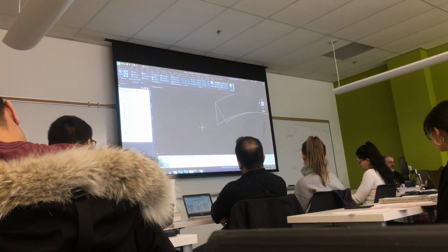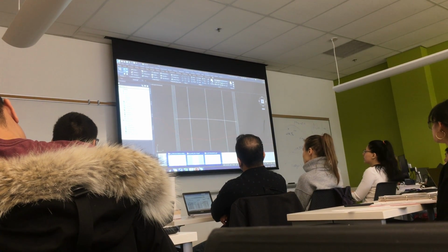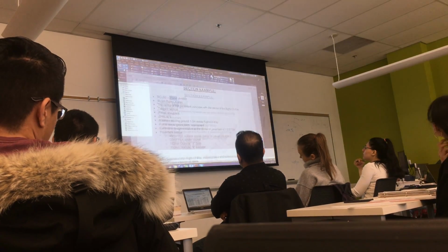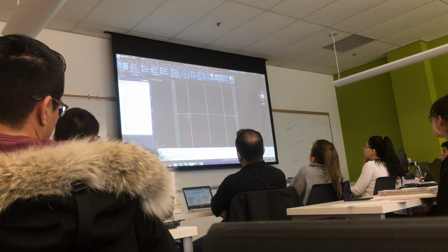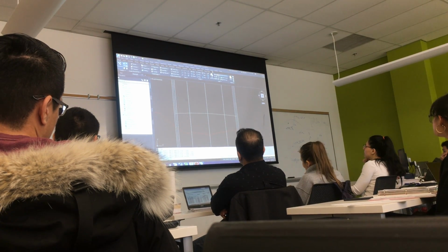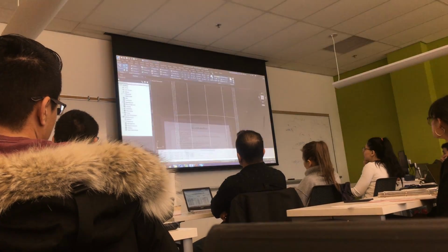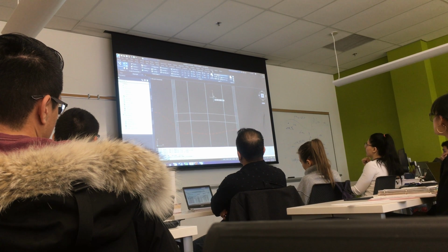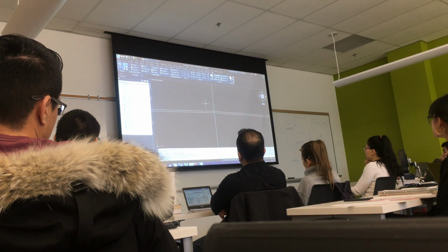So if I want those depths, if I go back to my design requirements, 40, 50, 150, 350. In meters, I'm going to make a copy of these two layers. And I know the shoulder has the same thickness. It says so right here. The shoulder is the same as the top, so 40 millimeters. So I'm going to copy these straight down 0.04, 40 millimeters in meters. So there's the thickness of the first top layer of asphalt.